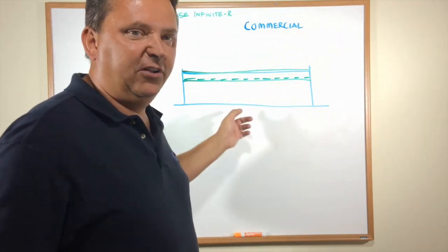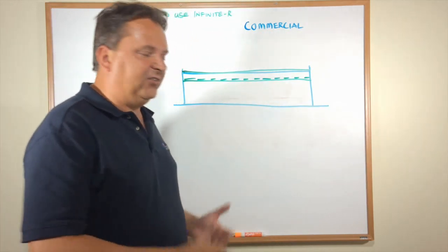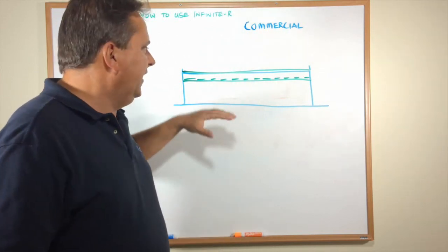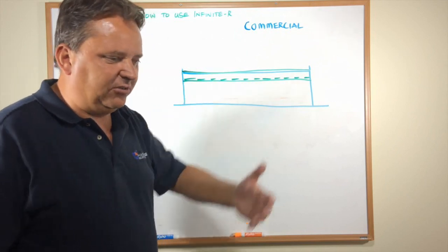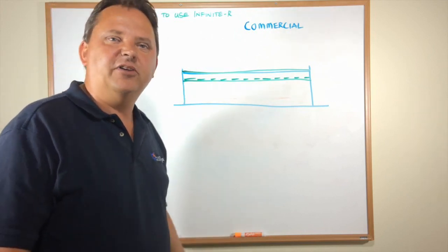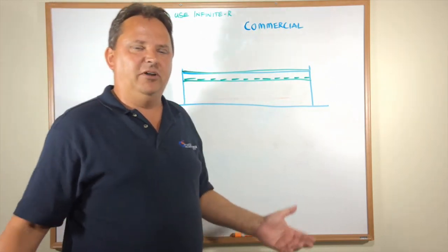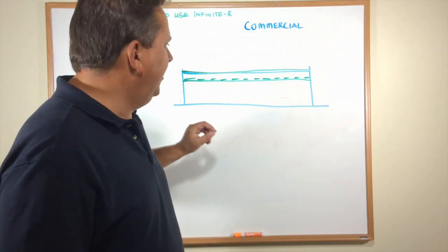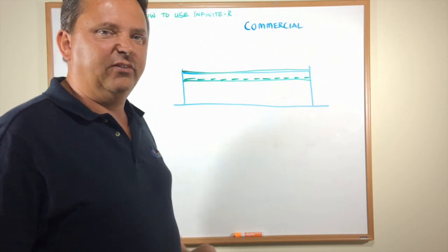It does another thing also. It allows for the excess heat inside the building to be absorbed and conserved for later, or helps reduce the peak demand of the air conditioner and allow the air conditioner to remove that heat at a point in time when it's not as loaded down, and therefore giving energy savings. So the second option is always to put it above the ceiling tiles.